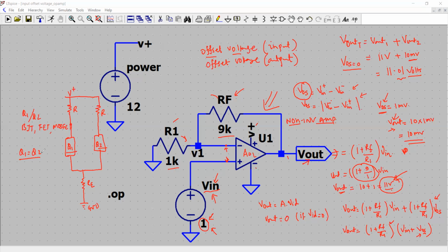However, due to manufacturing tolerances and changes, the two devices are not exactly equal, and therefore resistors are also not equal, and therefore you have mismatch amongst the components and the devices. Therefore, you have this output voltage always appearing at the terminal, even though there is no external input, even though the V in is equal to 0.